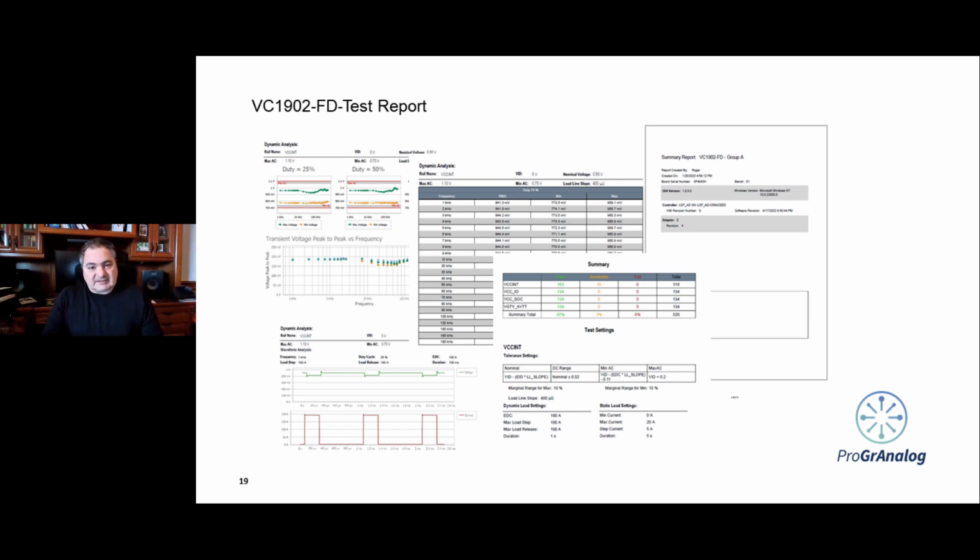Obviously, everything we send out is calibrated and measured, and there's an annual calibration. But you want to coordinate it with an oscilloscope because you might want to take a measurement somewhere else on the board. You're busy debugging other elements of the board, right? So you want to get a trigger from us and trigger an external oscilloscope. You want to sequence an oven, do some oven testing, or vary a bench supply which is powering the input to your power supply, and sweep that so you get some margin.